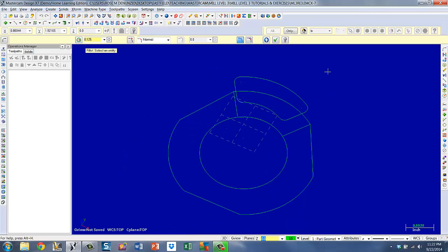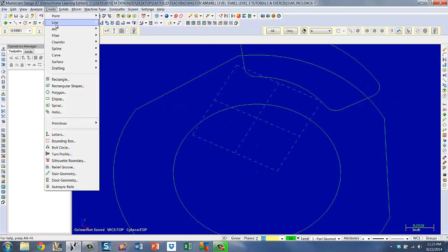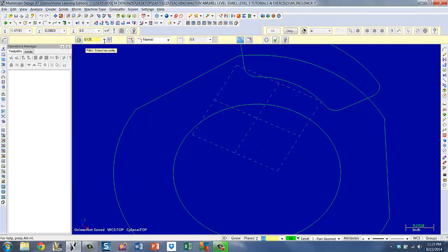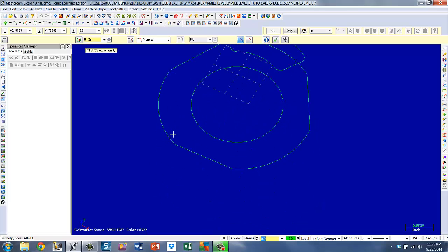Those are in. I can also put the 0.125 fillets all around everything. I think before I do that though, I'm going to check out of this operation and I'm going to delete these extra lines. They're no longer needed, just for clarity. Go back to create fillet entities 0.125. We have a fillet there, there, there, and two more.